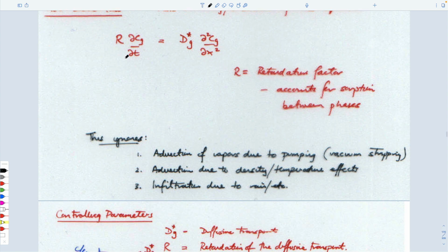And so what we need to do, I guess, is figure out exactly what these equivalent components are. What is the magnitude of the retardation coefficient that affects this? And what is the effective diffusion coefficient of the vapor in the gas as it travels within the porous medium?